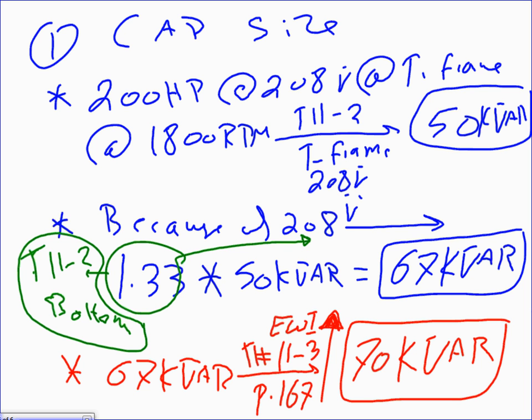Do you see it, Mr. Bell? So we're going to the next standard, 70. We still haven't sized the equipment. From now on, we're only going to be carrying about 70K var. Everything is for 70. I guarantee you some people, when they take the test, are going to take the 67 and find the full load current for the 67. You're done with the 67. 67 is a calculated value. Now you're going to size everything based on an actual industry standard.